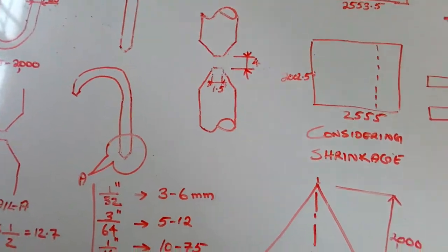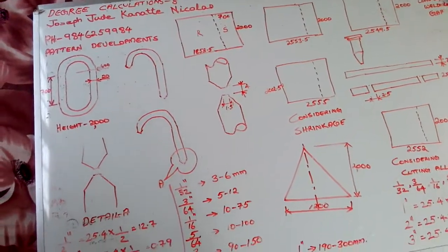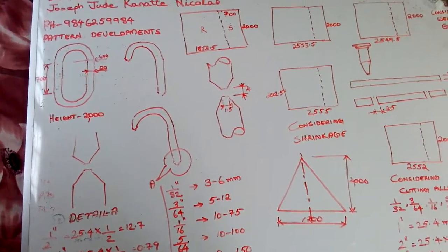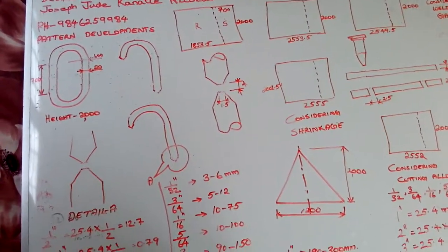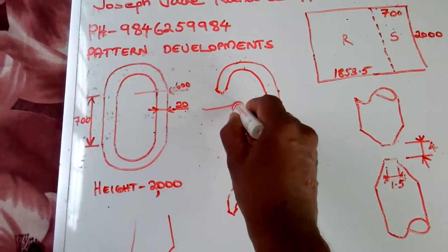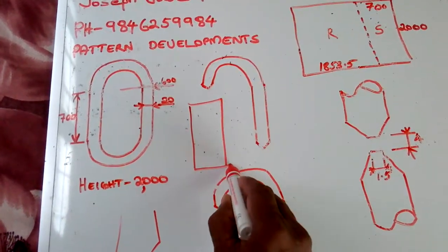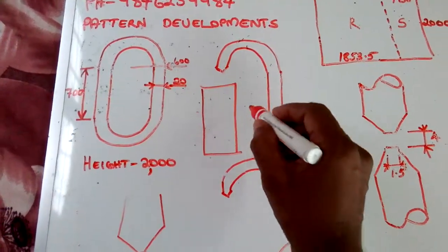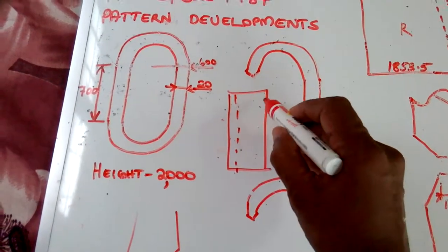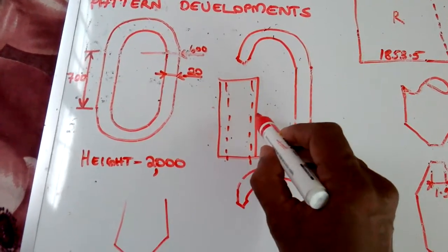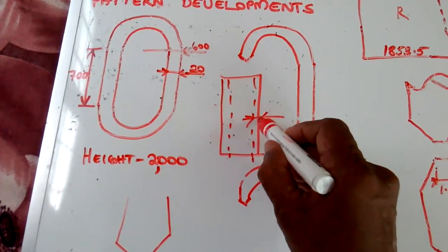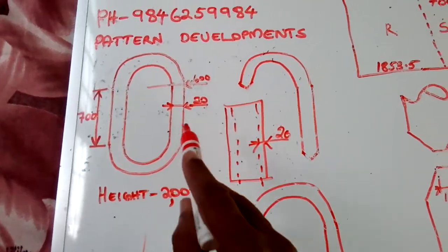Actually, most of the persons among my viewers know about this elevation, and on the top side no welding comes, but somebody may not be able to understand. So I make a small elevation here. Its elevation I have been indicating here. There should be one dotted line. How much is the distance from this dotted line to this thick line? It will be 20 mm, its thickness is 20 mm.